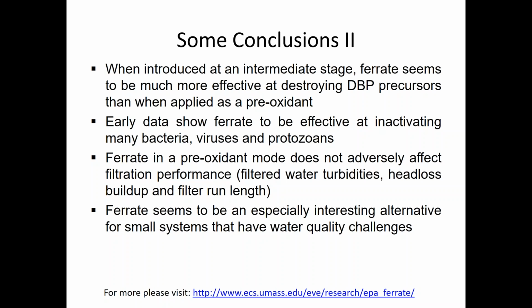Ferrate, in a preoxidant mode, does not seem to adversely affect filter performance. This is important and something that really needs to be addressed a little more than we have already, but the indications so far are pretty good, that it's a lot like ozone and it can often improve filter performance when added as a preoxidant.